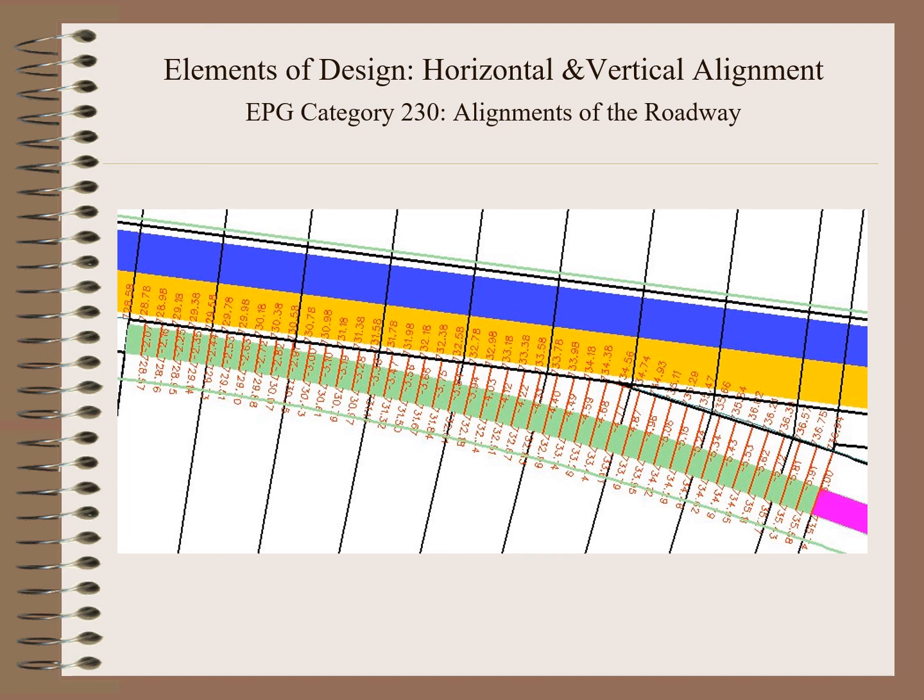In this picture, which is from our Road 2 class, you can see that we have elevations along the main line edge of pavement. We're taking that edge of pavement elevation and projecting it down with superelevation to the ramp baseline. And we utilize that information to calculate a proposed profile for the ramp baseline.